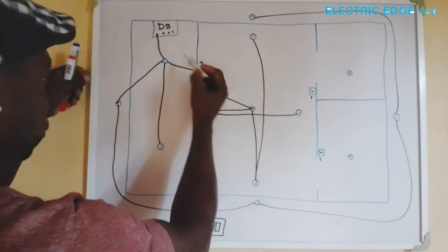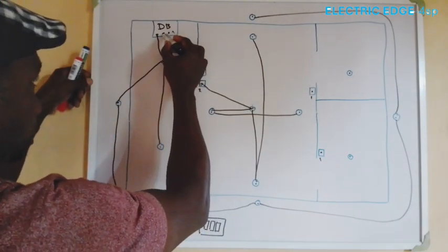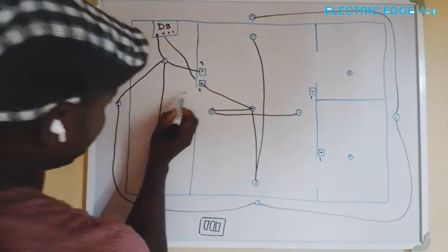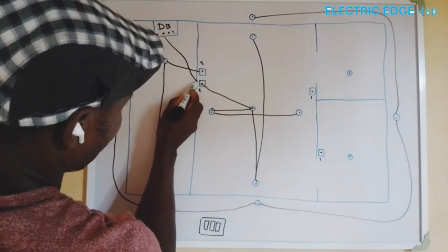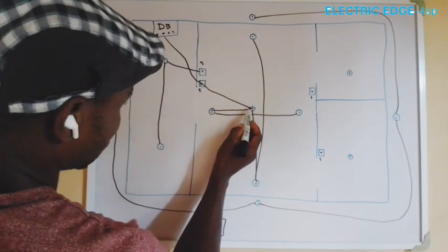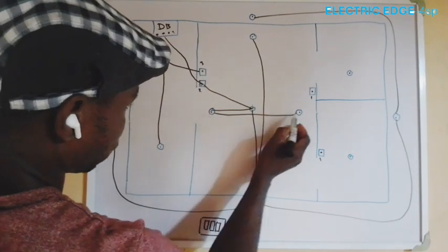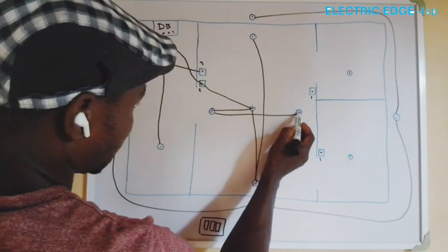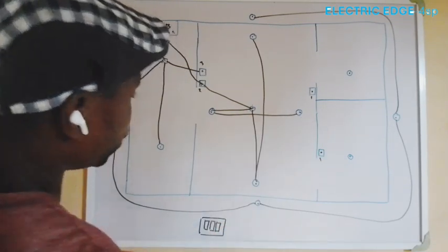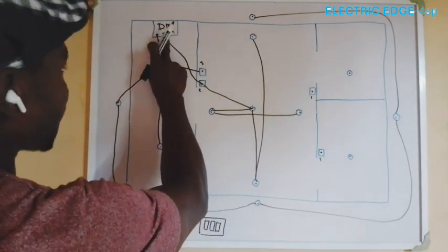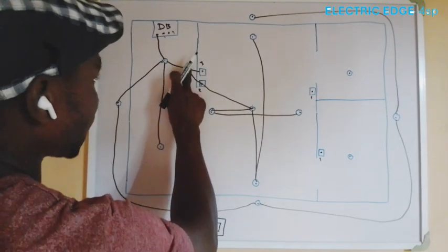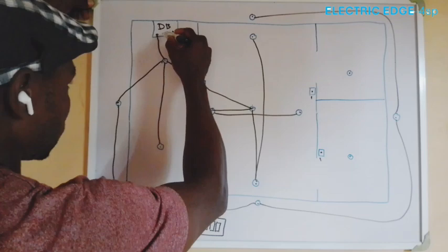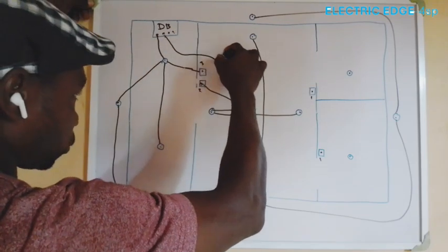So let me start with our circuits, our conduit pipe coming to this point, visiting this. From here we'll go to this, and from here we can travel from here. Our mains can either travel from here, in which case we may decide not to go that way. We may decide to come to the switch, to the center box first.